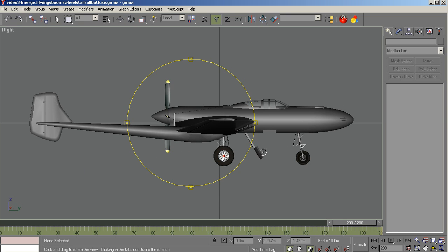turn on the grid here, to get data for your aircraft config. We need all kinds of data. We need the pilot's eye point or viewpoint, so that when you go to the virtual cockpit, you're looking out through the windshield at the proper place, left and right and up and down, etc. So we need to collect that eye point data or view data. I think it's in a section called views in the parameters eye point. So you get your XYZ coordinates for that.